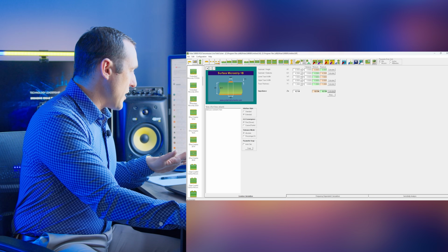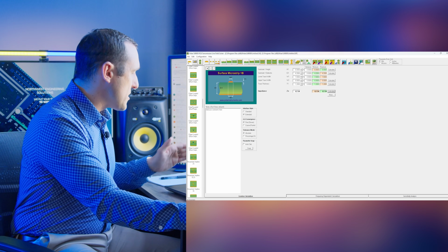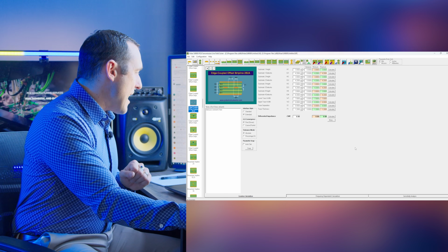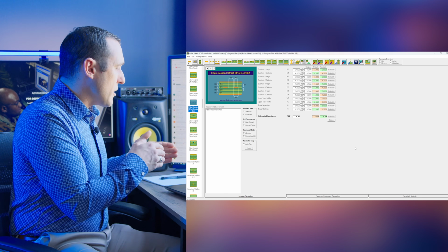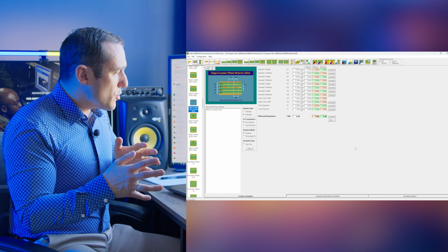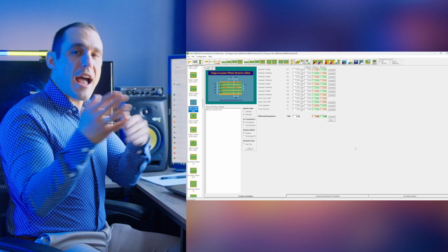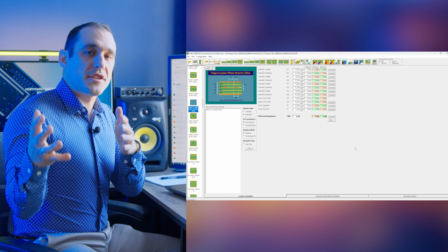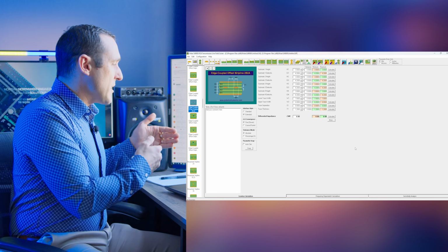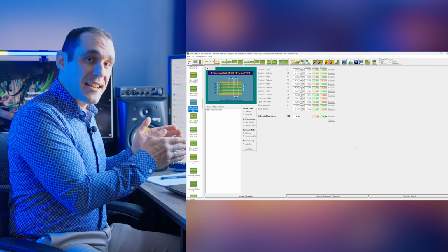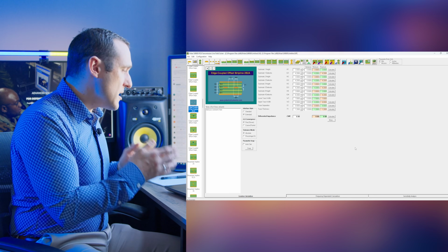Now, as you scroll through on the left panel, you can see a variety of different trace configurations, both single-ended and differential, and they do that because there are built-in models for each of these different configurations, which are then used to calculate the impedance. So that's really important. Again, you're not having to build these 3D models yourself like you would in a 3D electromagnetic simulation tool. You're using something that has been built in and validated against experimental test data, and that's what's being used to calculate the impedance in these models.